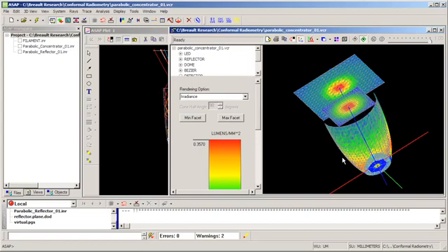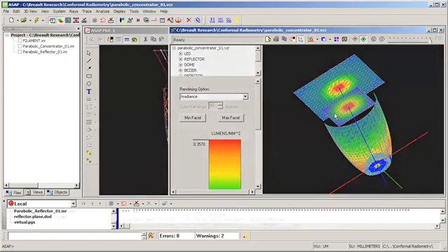In addition, users can now also add arbitrary surfaces, including transparent surfaces, which can act to monitor the radiometric parameters at any point in the system while having no effect on the resulting ray trace. In essence, adding transparent detectors to the system geometry.